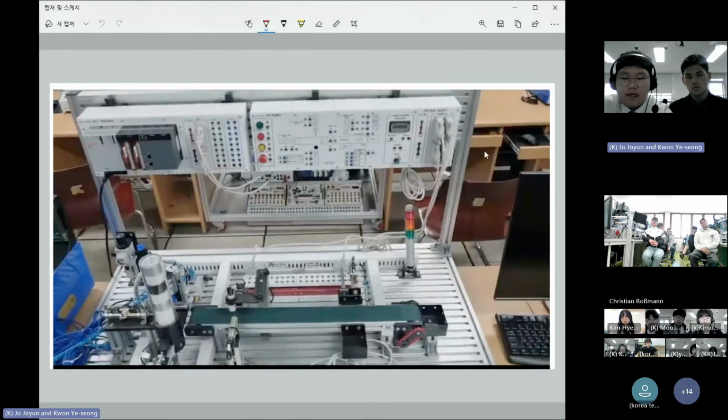Now let me explain how each cylinder works and how they are connected in the process. The supply cylinder moves raw materials such as small parts or blocks from a storage area to the processing position. When activated, it pushes the material into place. After that, the cylinder retracts and gets ready for the next material. This is the first step in the process.